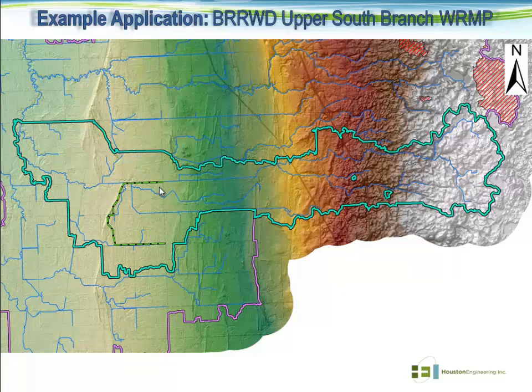Now, as you can see here, this is one location that we had identified. The green dashed line correlates to a potential embankment alignment that we had identified. It's trying to use this existing escarpment that you see right here, and also back water up in this particular region at this location. So when we take a look at that with the hydro DEM again, we can derive real quickly what the project watershed would look like, or what the area would be that would feed this particular retention location, which you see highlighted here in the yellow line.